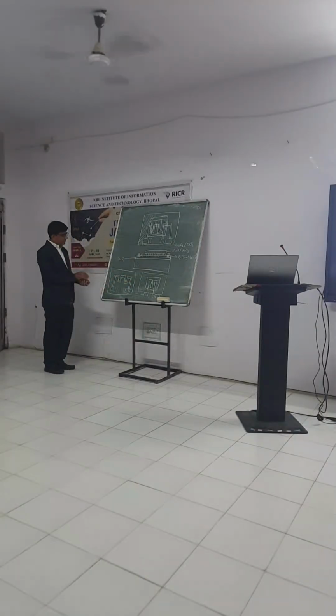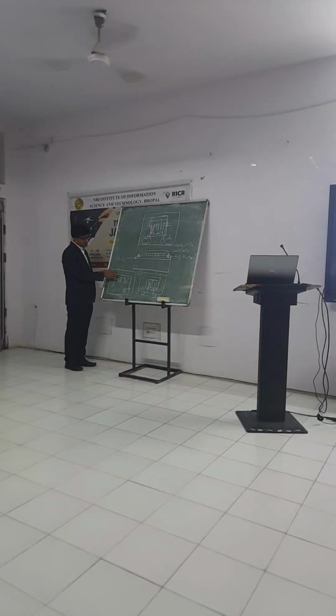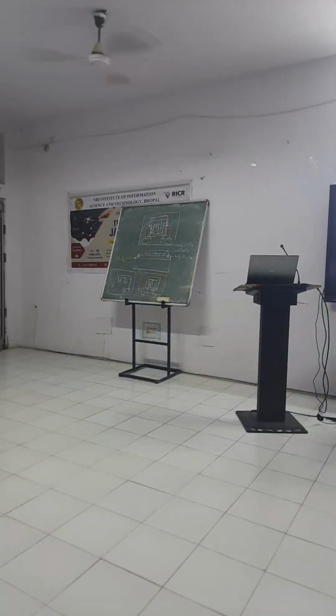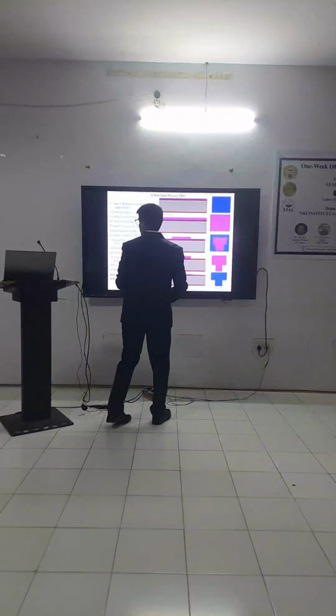Understand? What will happen? This complete nickel chrome will be etched out. Because why? Because in this area I have a photoresist. So this nickel chrome will be intact, and the remaining nickel chrome will be etched out because of the etchant of nickel and chrome. So similarly here you can see this photoresist will protect your nickel and chrome below it, and in the remaining area your nickel and chrome will be removed, and finally you have nickel and chrome only below the photoresist.